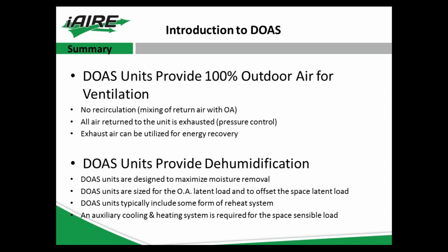And then finally, the DOAS unit is generally used to provide dehumidification for the space, not necessarily space cooling and space heating, although you can use it to offset latent loads or sensible loads, depending on your building, depending on the application within that building.